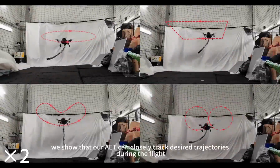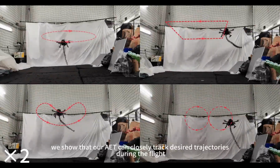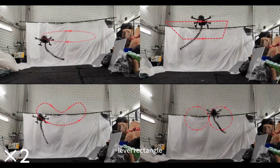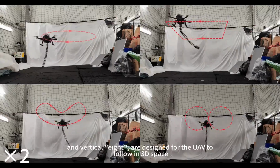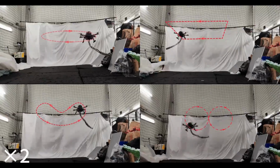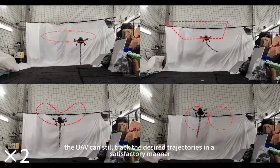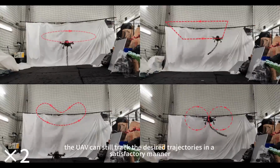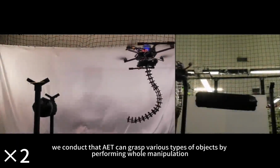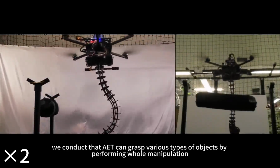Next, we show that our AET can closely track desired trajectories during the flight. 4 different trajectories, level circle, level rectangle, vertical heart, and vertical 8, are designed for the UAV to follow in 3D space. Although we arbitrarily swing the continuum arm, the UAV can still track the desired trajectories in a satisfactory manner. With the shape deformation capability, we show that AET can grasp various types of objects by performing whole body manipulation.